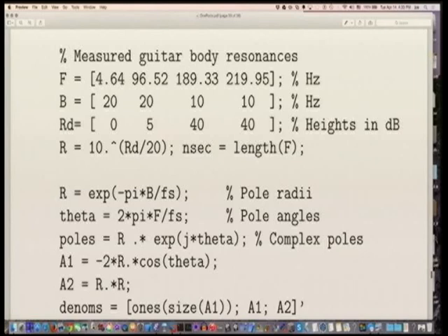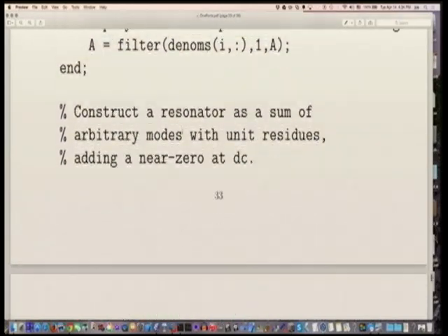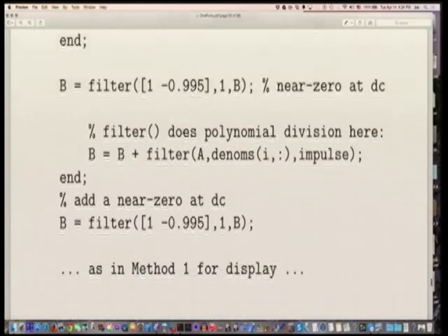So I typed in the frequency. Look, I'm actually modeling that low frequency thing. I don't know why. So I've asked for a pretty high Q here. So this is a Q of about 5, right? And that is, oh no, these are higher Qs. So yeah, this is actually just operator error. I've actually specified a higher Q for the higher resonances. So this is something that just needs to be redone. I don't remember running into a problem. I think I just didn't pay attention to the relative Qs. So that's just design error.